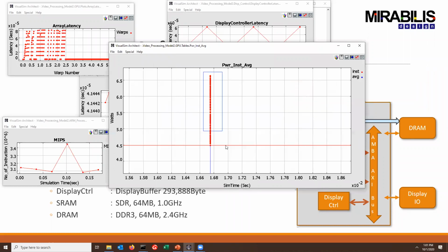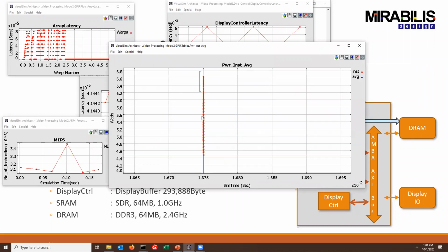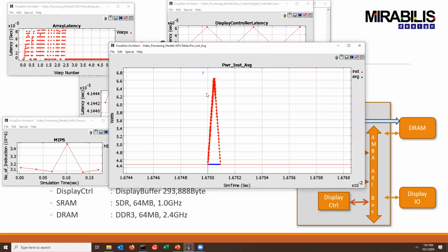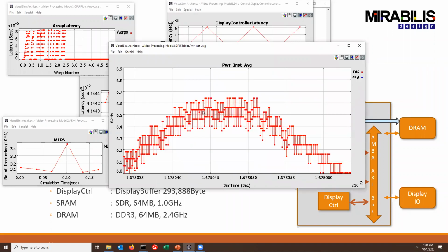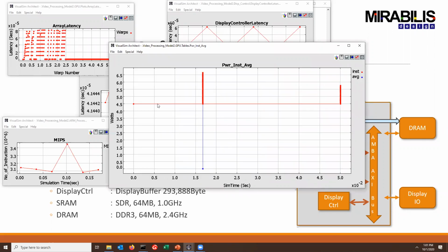Why is that important? The reason that is important is because that helps me figure out, are there ways I could offset some of these stats? So if I go in here, you can see it's almost about 7 watts of power. Like down here, 24.5. So I have almost like a 40% higher power. Now, if I could push that down a little, I could be saving a lot of thermal cost because my cooling cost would go down.